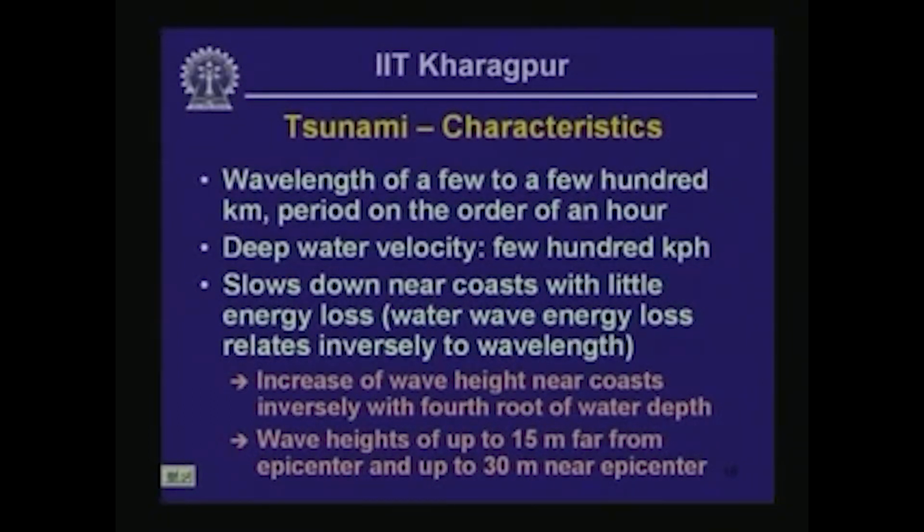In the process, the wave height is going to increase near the coast, and simple calculations show that the wave height increases with the fourth root of water depth decreasing as you approach the coastline.